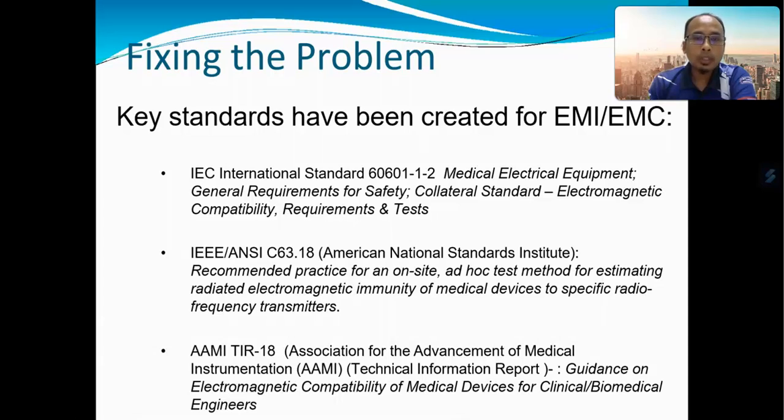So basically, in order to make sure that the developed medical device is within the standard of EMI and also EMC, we can refer to these three standards, which are IEC 60601-1-2, IEEE ANSI C63.18, and AAMI TIR-18. These documents are very important in order for us to ensure that the developed device follows the standard.